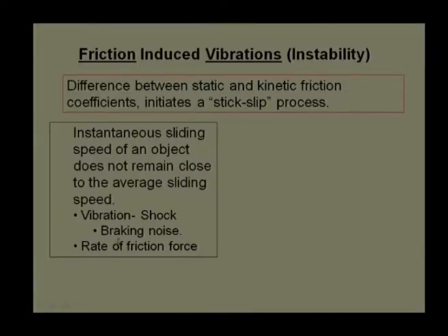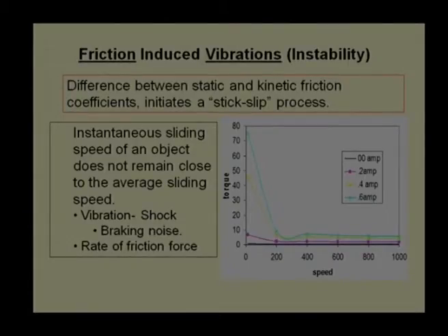It largely depends on the rate at which the friction force is applied. Is it applied very fast? Is it applied gradually? That decides whether there will be friction instability or not. To elaborate on this, I am just showing a couple of results from experiments we have done on one brake material.